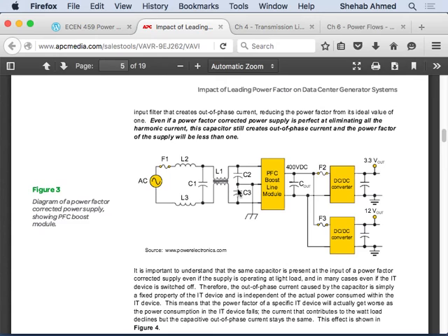If you have a utility like Qatar Petroleum, and your feed got disconnected for some reason, there's a disruption there. What's going to happen? You're going to turn on your generators, and your UPS system will kick in first. You will have no problem. The UPS will feed everybody, and then as soon as your standby generator comes on board, you will probably turn off the UPS because you're fine. Everything is fine now. But this generator is going to see all these leading power factor loads.